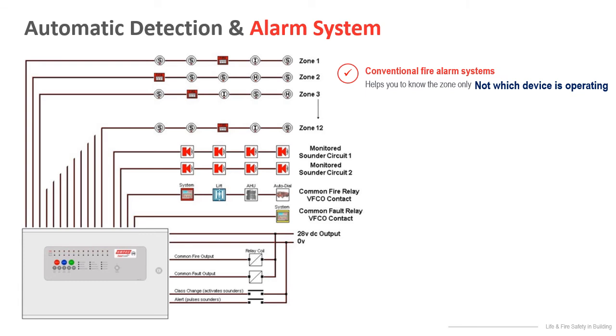Within the system, the intelligence resides in the fire alarm control panel. The panel receives a trigger signal from a conventional detector or initiation device. The designer must be sure that the last device of the circuit has sufficient voltage to operate within its rated voltage.